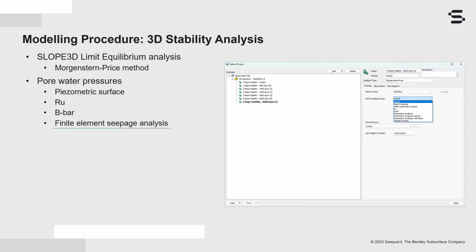We will use this final option such that stability is computed given the pore water pressure results at select times from the seepage analysis. These times do not really represent actual time, but variable pore water pressure conditions in the heap leach pad from saturated conditions to the long-term steady-state conditions given the annual average infiltration rate applied at the surface.